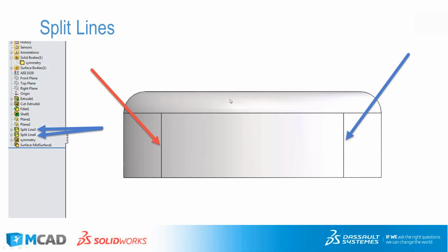Another use for them is for when you want to get results from only a certain point or you want to fix something in only a certain point. Obviously, if you have a face and it was spot welded on a couple places to somewhere else, you don't want to fix the whole back face. You want to fix just those spot welds that fixed it to the face so that the simulation will be more accurate. And you can do those by making the little circles on the back to simulate where the 4 spot welds would be and then use that instead. So that's just a way to make your sims much more accurate and avoid the headaches of seeing unrealistic results when you just sort of generally apply a force.